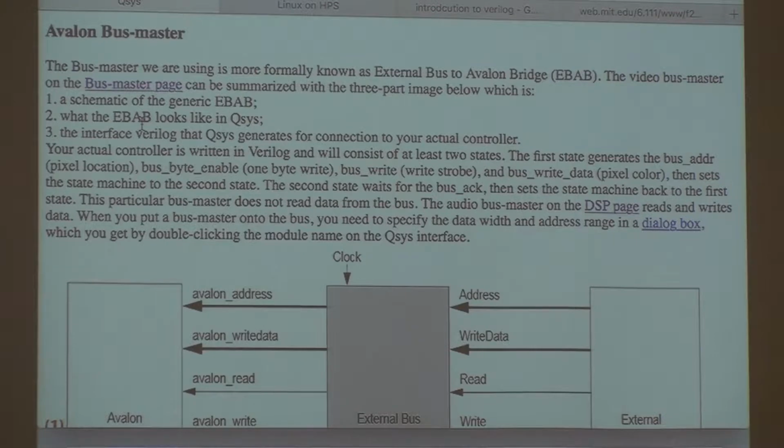So if you're going to read the audio and do some digital work on it, let's say you want to do speech recognition, or you want to make a speech vocoder so you can do pitch shifting, you would read that channel at 48 kilohertz average, but it would be bursty, do the calculation, and then put out the audio signal again onto the audio codec. So you have to be able to do a read-write.